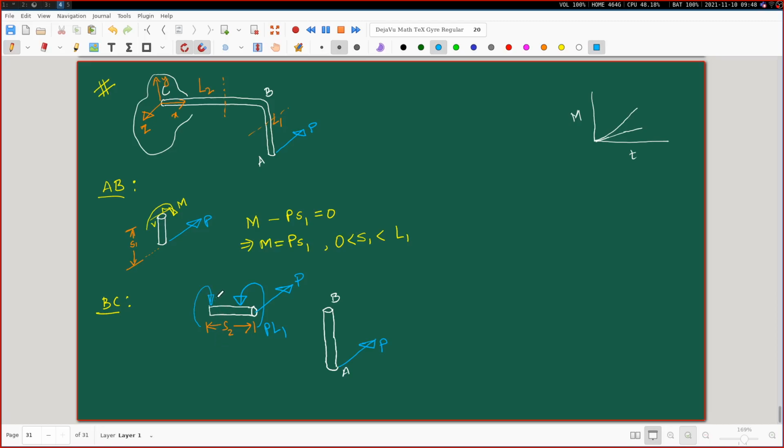But in addition to that, I'll draw that a little bit later, there will be a bending moment. Now that bending moment, I'm going to draw a curved arrow. You tell me on which plane, referring to this XYZ axis, should I draw that curved arrow? XZ plane. Very good, XZ plane.